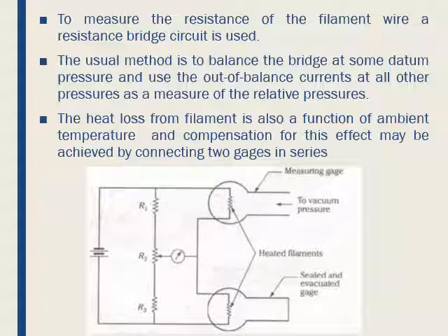Similar to this, even a thermocouple vacuum gauge can be used, which creates a resistance, and that resistance variation we can connect to the output EMF source and compare with the input EMF source, and the voltage across the output EMF source can be calibrated in terms of the pressure.